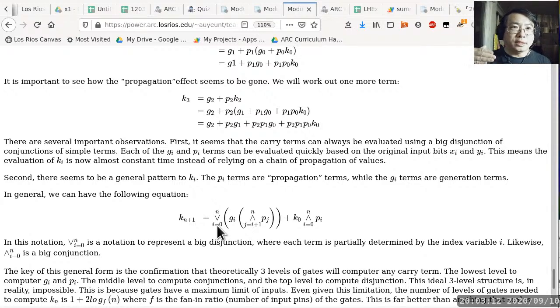It allows you to specify code in a C-like language, and then it cranks out the quote-unquote object file from this compiler, which is basically a lower level specification of how gates are connected. That specification gets compiled again by a silicon compiler to figure out the connectivity of the transistors, and then from there you have a router to figure out how to route electrical signals between the transistors, and after that you actually get to the die design.